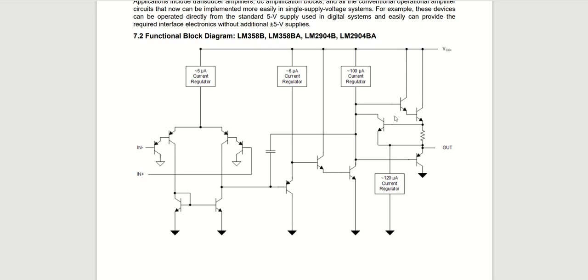And here's another Darlington array that goes into their output stage. So it's an NPN Darlington that goes into a PNP as their output push-pull. This, I would still say, is a little bit too much, and like I said, I would just keep it simple. And let's look at another one.